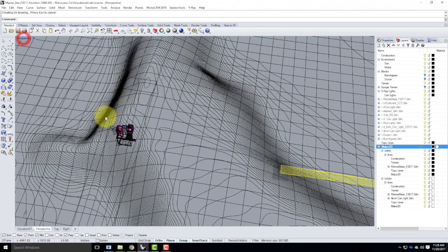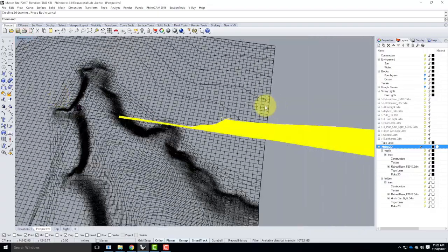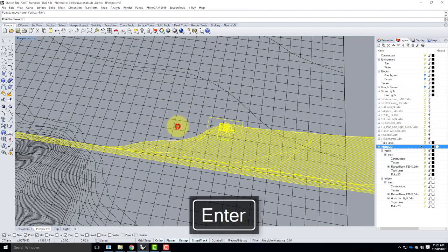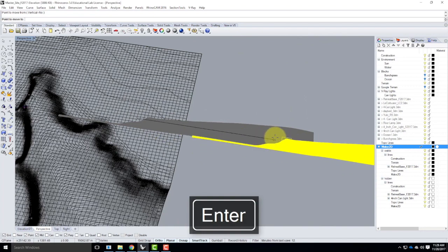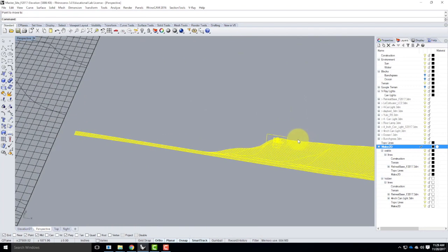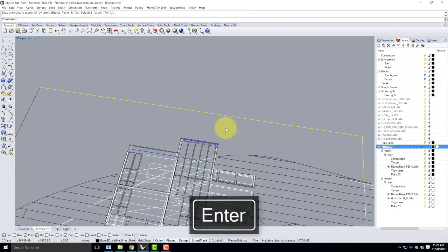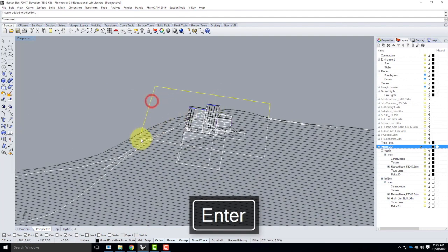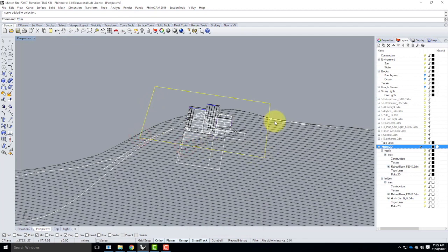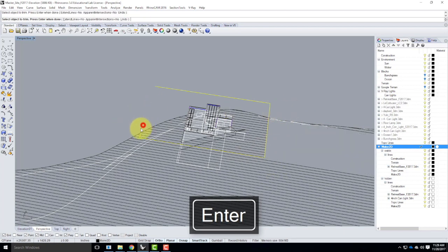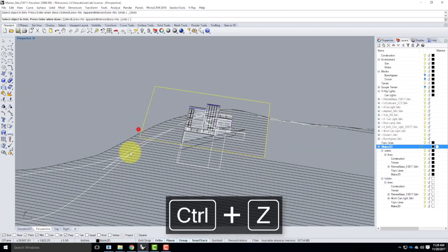Let me go look in the perspective view here. And this time, I have that box around my view, which matches up with my view. So let me move this away from my model for just a second. Like that. And then I can use this box. Let me go ahead and zoom selected there. I can select these pieces of my box, like that. And I can trim and get rid of the stuff that's outside of my box. Oops. Hopefully.